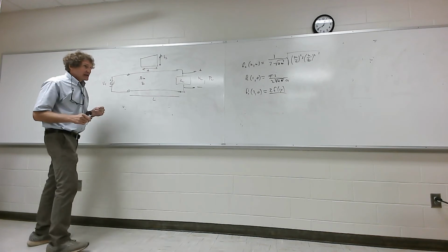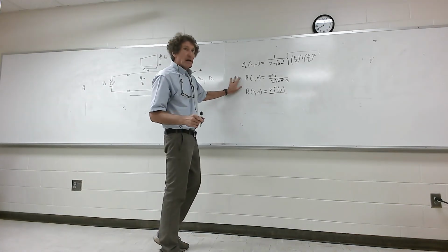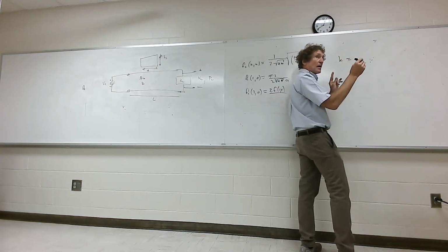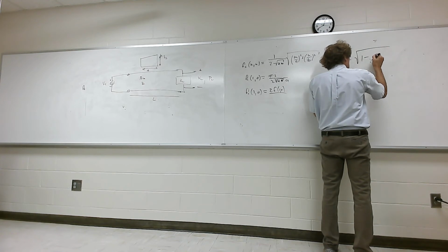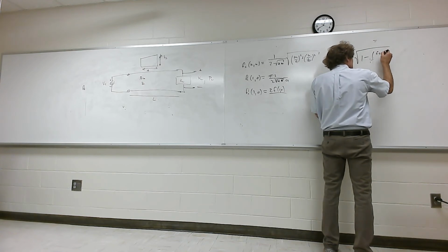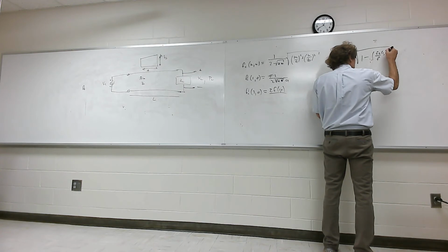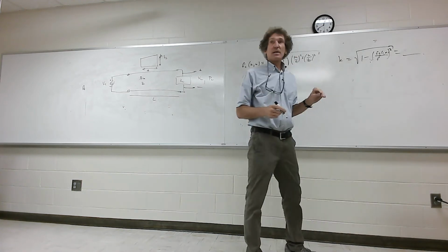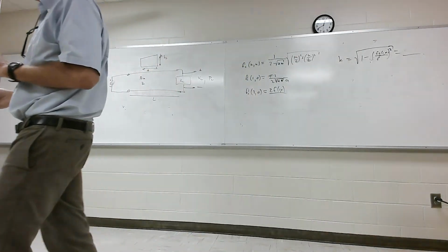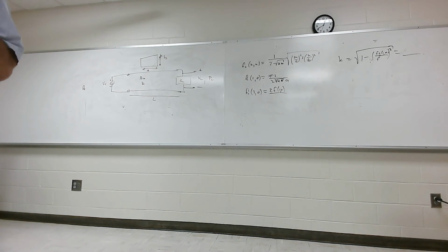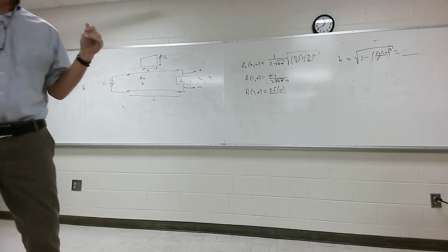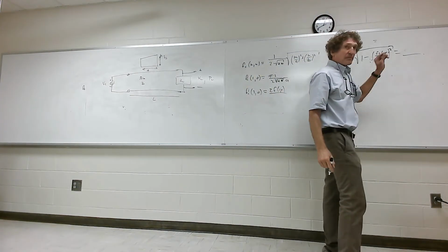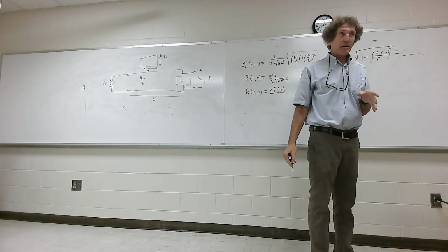So when I get this, and I know what this is, right? You got the 10. My next step is what? I call it k. And k is what? The square root of 1 minus, and it's really (fc10 over f) squared, right? And that value k is going to be less than or equal to 1. Hopefully less than 1. If it's negative, you did something wrong. If you get a minus j there, what you did is probably flip the fc and f. You probably messed that up. And it is squared. A lot of people messed that up. They forgot the squaring in that quiz. I remember that. Everybody with me on this?